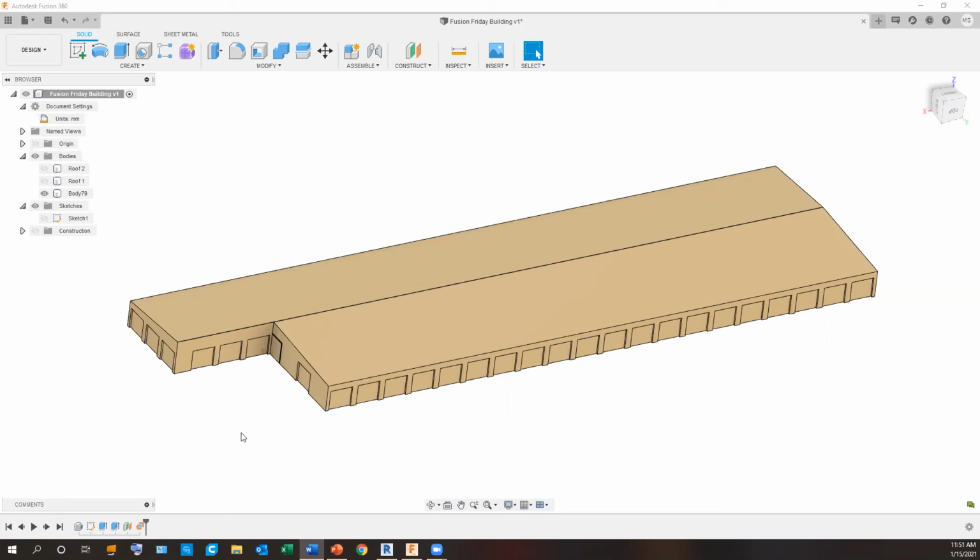And we found the most economical way is to eliminate a lot of that assembly time afterwards and just eat it up with the extra print time beforehand and print it with a lower selection of infill, or a lower percentage of infill. So you can do it however you want. Either way, we've done it all three of those ways, but the best way we feel is to just split it up into separate bodies and print it that way.